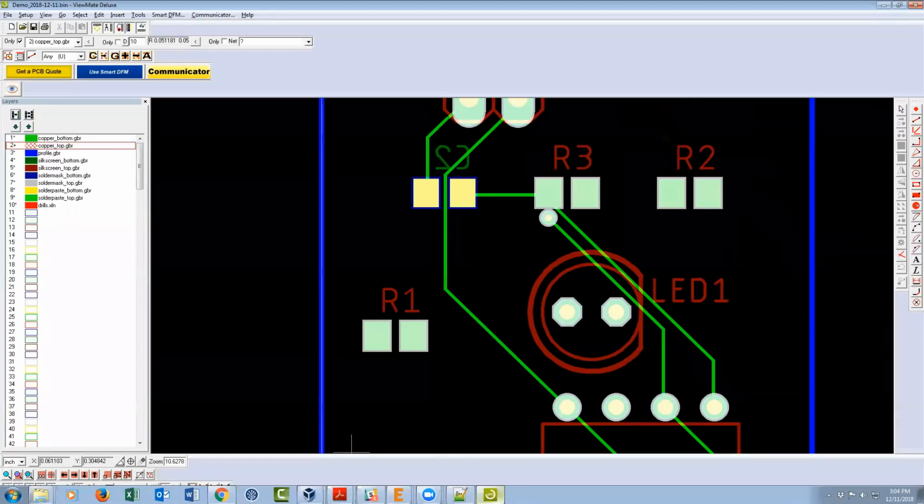Now, why is this? So the Gerber standard only recognizes vector fonts. It doesn't recognize any TrueType font. Basically, if you notice a PCB has any fancy text or any fancy silkscreen on it, they've either vectorized the font or they've imported that text as an image, because the Gerber standard on its own doesn't accept anything other than a vector style font.